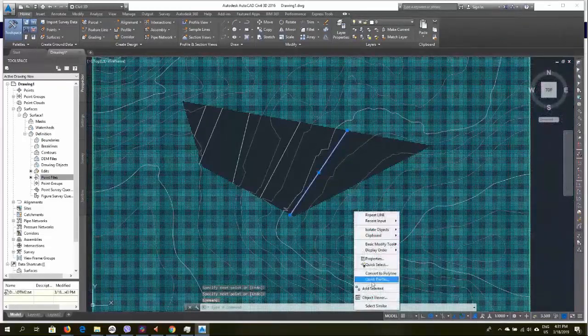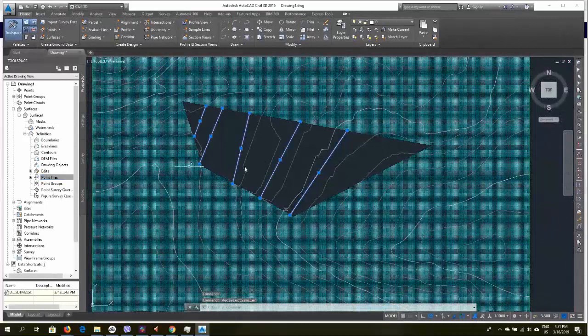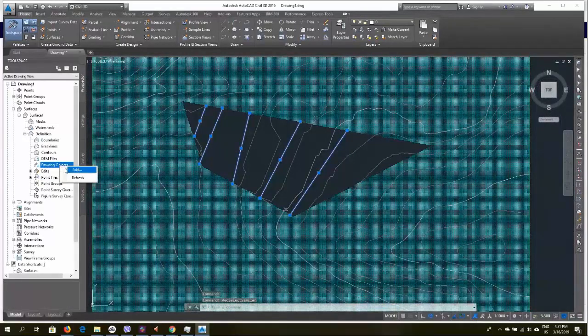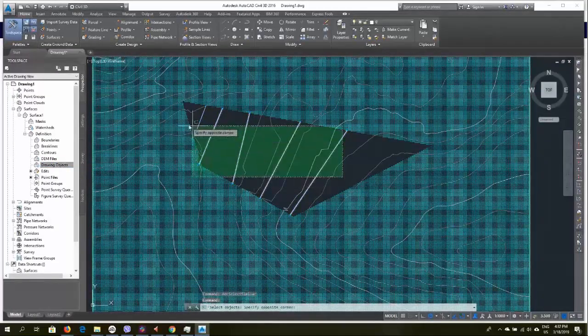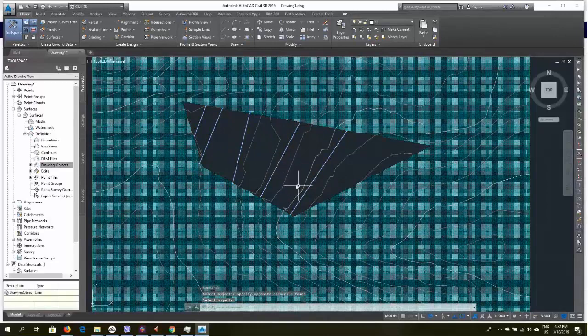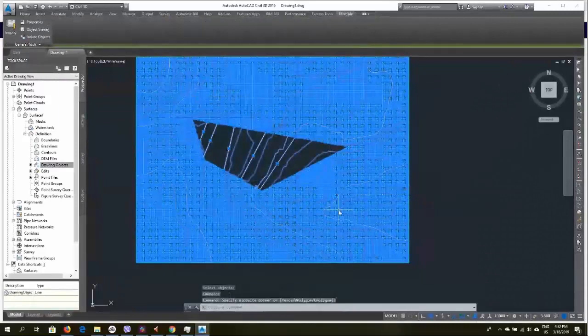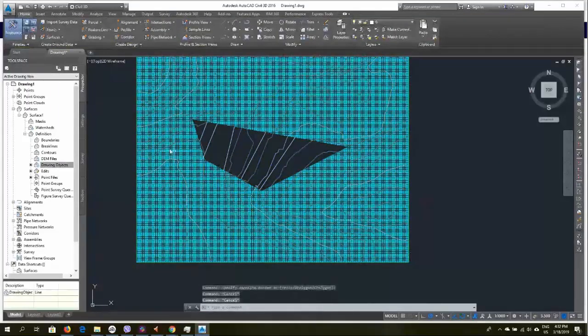And now we will add these lines to the surface definition. So this can be our manipulation of the surface now. Let's select these lines, right click to confirm. Okay, we can now even delete those lines. So to delete them, we need to do it like this.